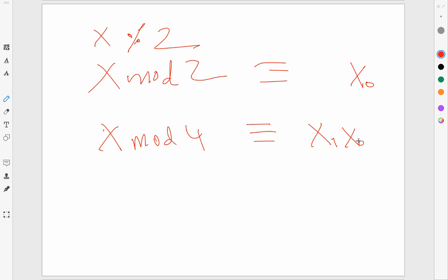What other solutions are possible, ignoring the cost for the moment? What other different ways can I combine these 2 to 4 and 3 to 8 decoders to create a 7 to 128 decoder? Two 2 to 4 and one 3 to 8, that covers all the 7 bits. Good. What else? Three 2 to 4 and a single bit by itself, that's another one. And I think that pretty much covers the space, because you have to use two decoders.